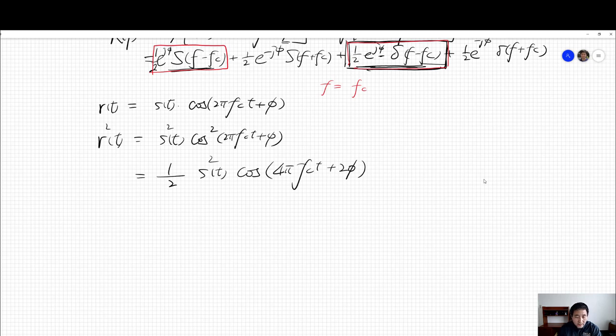So here we have S(t) squared. Now this is a positive signal, so it will have very little variation. Suppose this is a real number. If it's not, we use the absolute value squared. We indicate that by the average of the square plus a variation called V(t). We understand that this V(t) has much less variation than the received signal R(t) because V(t) is positive.